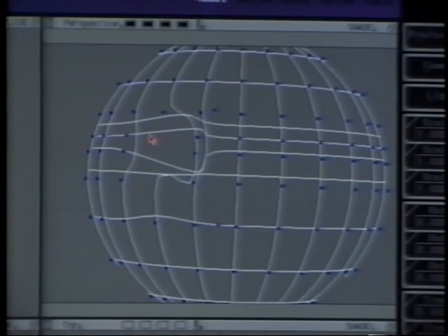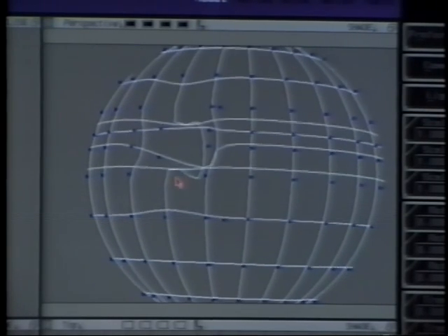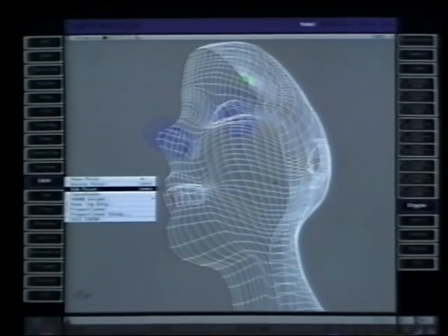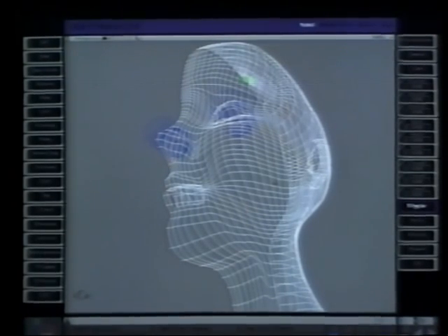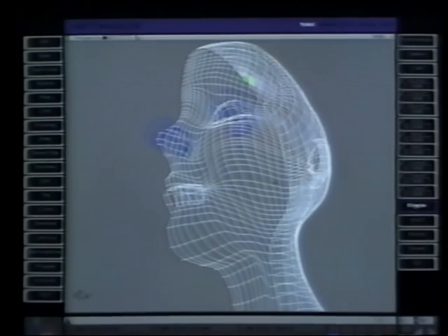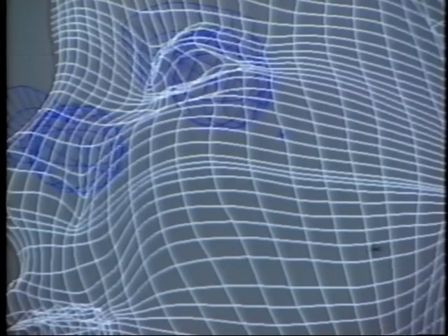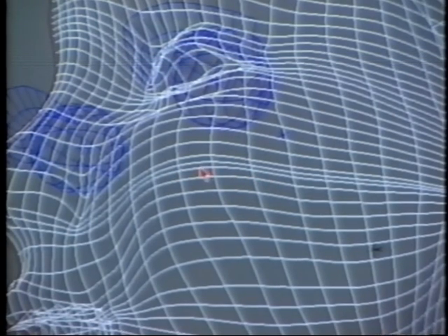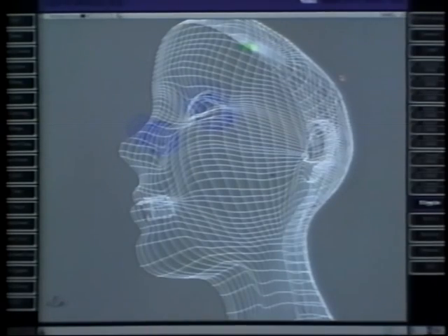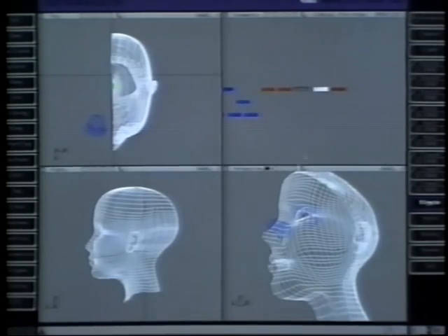Also, on a more complex model, inserting edges where you want them can sometimes mess up another part of the model. For example, if we're pretty far along in building a B-spline head and need more points in order to make nostrils, then that adds extra rows of points running across the cheek. We could manually drag the new points to smooth that area out again, but the dense area would still make editing the shape of the cheek very difficult, as well as possibly distorting the texture. So I'm going to undo a few steps here and try it another way.